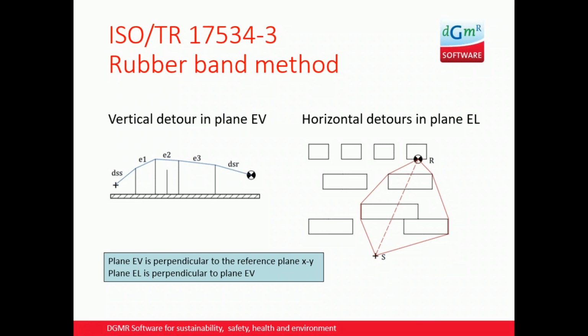Because in the original ISO 9613 it was not very clear how to calculate these detours, and that made the different implementations in CADNA/A, SoundPLAN, LimA, IMMI, Predictor, iNoise differ by up to 10 dB. While they were all within their rights, you can have a large difference, and this makes it better and more clear. There are also other parts in the quality assurance method, but this I think is the dominant part.